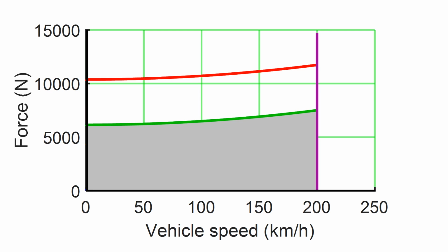To not require high acceleration on uphill gradient significantly reduces the required powertrain operating area and reduces the cost. Note that if we increase the acceleration required on a flat road, the vehicle will automatically get better acceleration at gradients, and also the possibility to climb even steeper gradients.